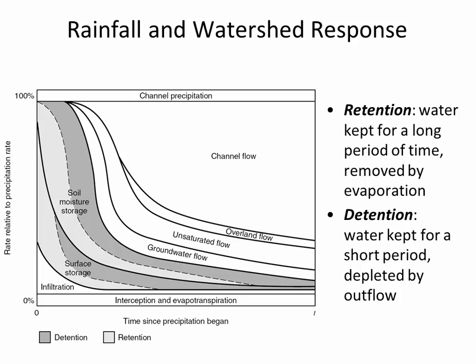And once there's groundwater flow, meaning that the saturated zone is high in one place and lower in another spot, like it's not level anymore, so the water is moving side to side, then actually the water will move sideways through the unsaturated zone as well.